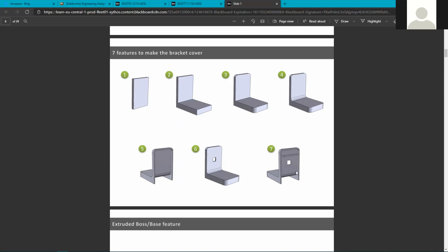The first thing is, what is this likely to be a part design of? Well, because of the thin wall that it's been constructed with, you can see the back of it is hollow, some thin walls have been left. I can pretty much safely assume that it's some form of molded part. Maybe it might be an injection molded plastic part, because that tends to be the method of design that you use for those sorts of parts. You make them out of thin pieces of material, thin walls, rather than solid blocks of material, which figure 4 is still a solid block.